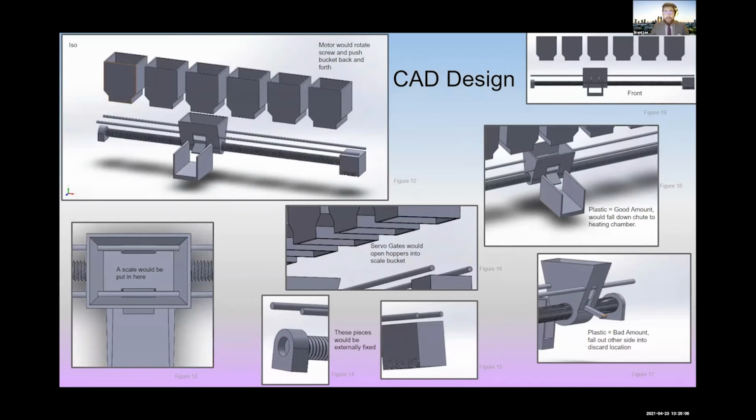All right, this CAD design is a fleshed out model of our hopper and weighing system. It's designed to be 3D printable where possible, so the materials can be sourced. If they can't be 3D printed, they can just be replaced with scraps, like a bucket or a repurposed 2-liter. But it's designed to be used with a stepper motor to control the carriage down there. And then the carriage is equipped with a scale to determine either good or bad weight of dispensed plastic.